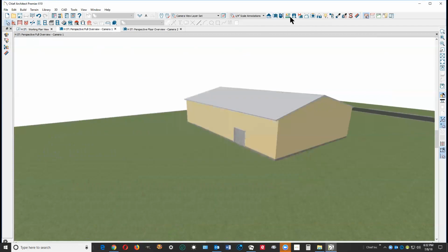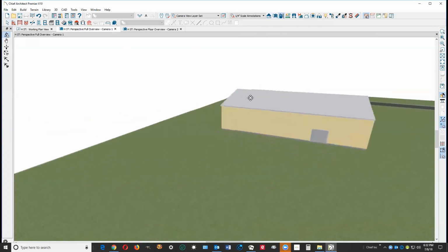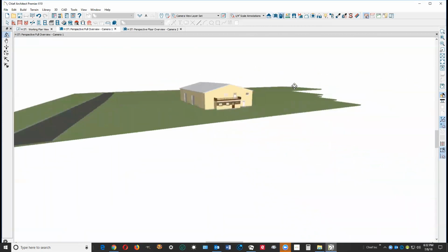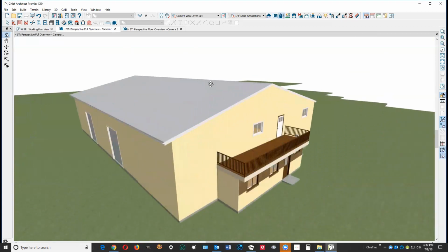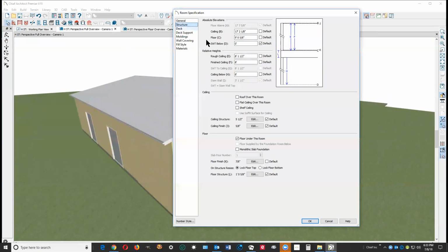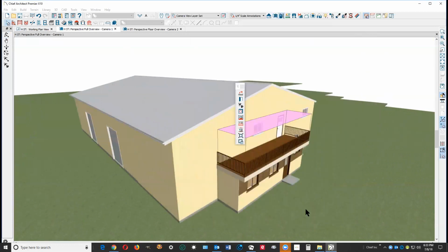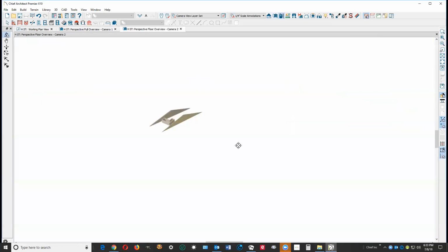So this seems to be all cleaned up, and you should be ready to finish it up and go to layout and create your elevations and so forth. One thing is with the deck here, same thing here. It should be set at -3 for drainage purposes, so that the deck is lower than the entry door. Otherwise, with a heavy rain, water will just run into the inside the building, and you don't want that.